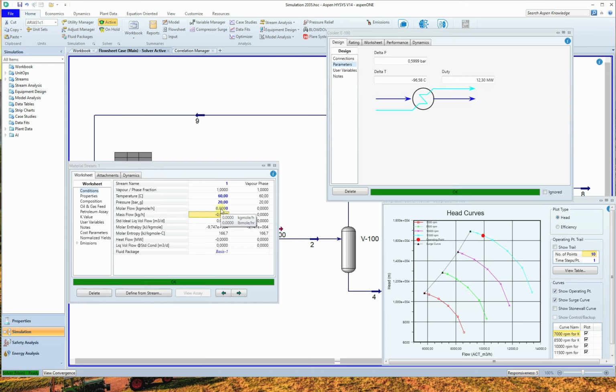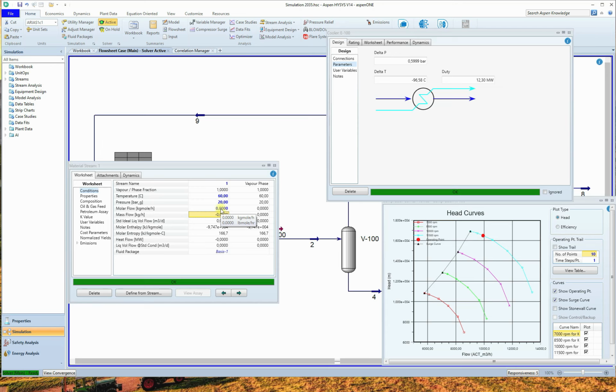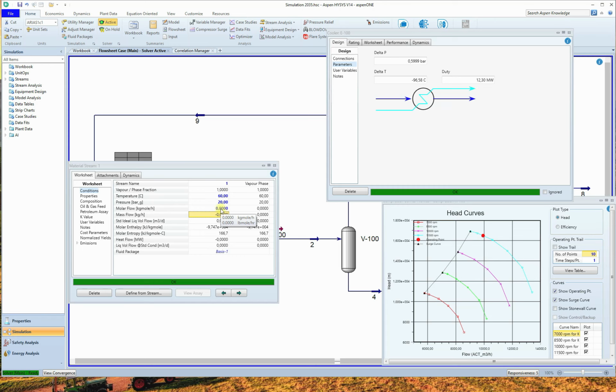In some cases, the full recirculation case can be dominating for pressure drop. Also, when you are changing the conditions for an existing cooler or a compression loop, and especially changing the bundles for the heat exchanger or the compressor, you need to check the hydraulic capacity of your heat exchanger, and implementing this resistance factor is a very good way to predict the pressure drop more realistically.